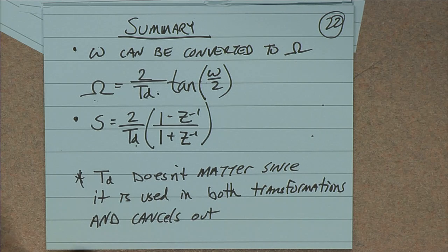I've never seen this written out, but they took H(s) and wrote it as a differential equation. If you think back to maybe circuits or some other class, we could solve these circuits using Laplace transforms. Where do those come from? Well, you had a differential equation that described the circuit, and you could use Laplace transforms to solve it. Some enterprising people decided, hey, I can go straight from the differential equation that describes H(s) to H(z) by using trapezoidal integration to do the integrals to solve the equation. Now, I've never done it. I've never even seen it done, but supposedly that's why it was there originally.